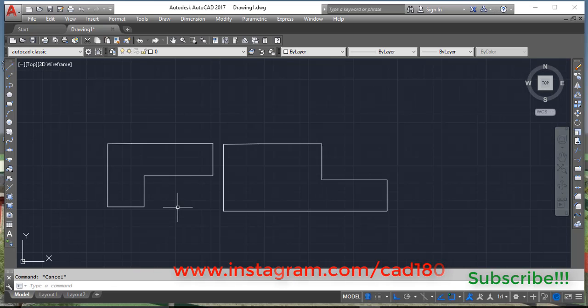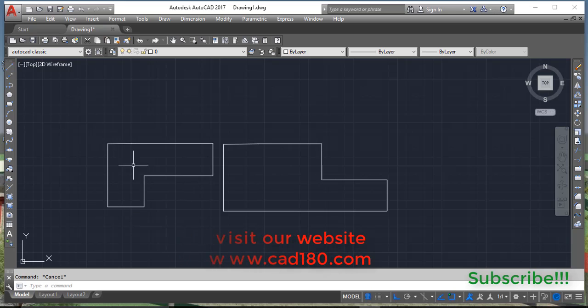So how can you convert a line to a polyline and a polyline to a line? A line which is partly divided at some points and is joined into one line is called a polyline. And if you break the polyline and convert it into lines, it makes partitions of that polyline. So first of all, we are going to join the partitions of the line that we drew, and convert it to a polyline.